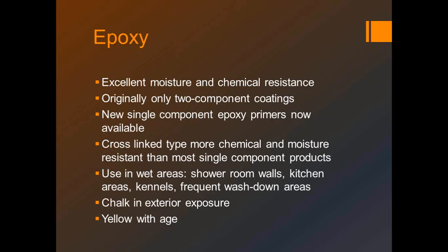And again, it's dependent upon what you want to achieve on that drywall. We can get a very moisture-resistant finish on the drywall, but drywall is not going to necessarily be very moisture-resistant in and of itself. So it depends, again, what you want to accomplish with the system.